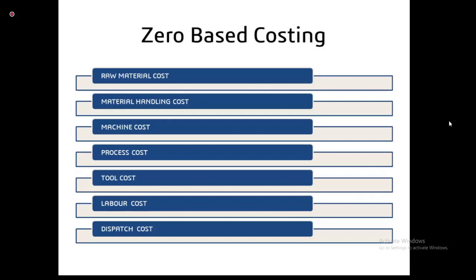Secondly, whenever you are doing costing, you have to consider how many manufacturing approaches are going to be carried out on the component, because that decides the machining time, that is, the aspect of machining involved in the product. Say, for example, if I am going to machine a component, first of all I need to understand which manufacturing processes are involved: whether there is rough milling, contour milling, finish milling, or a drilling operation.